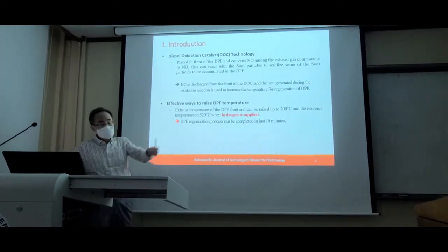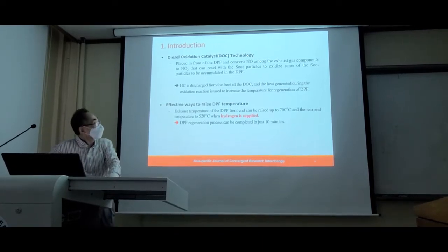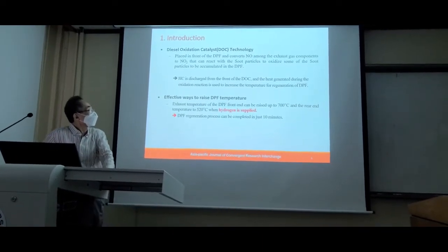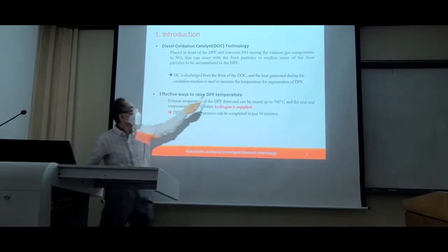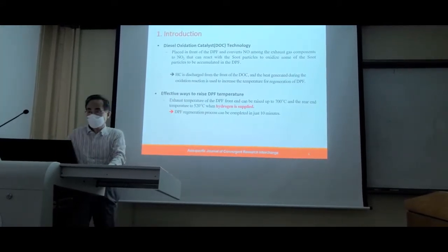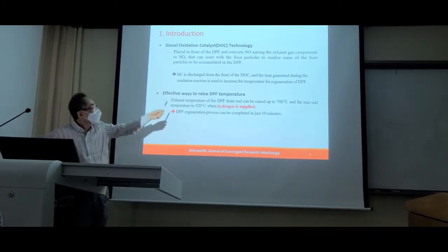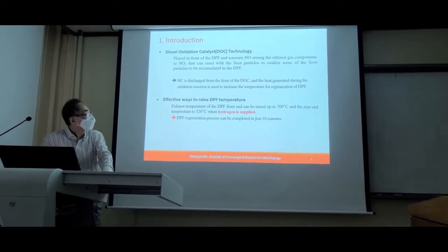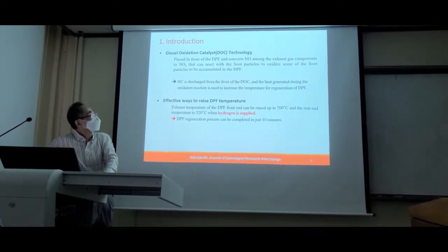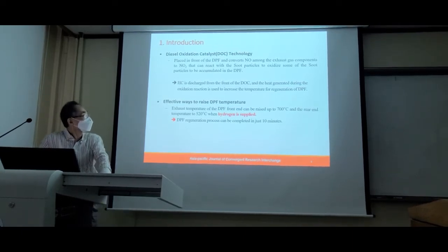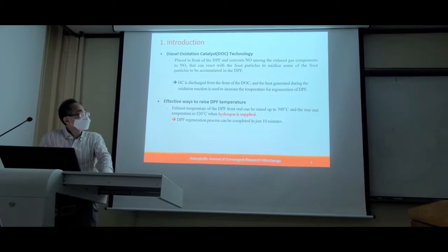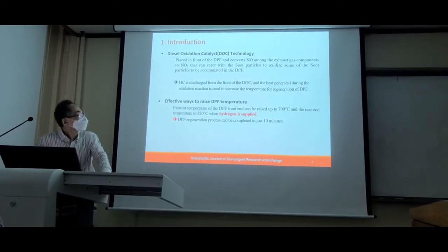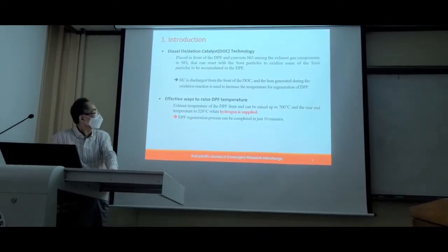And also there is another emission compound that can be handled through the DOC. It's called HC, hydrocarbon. It is discharged from the DOC, and heat generated during the oxidation reaction is used to increase the temperature for regeneration of DPF.